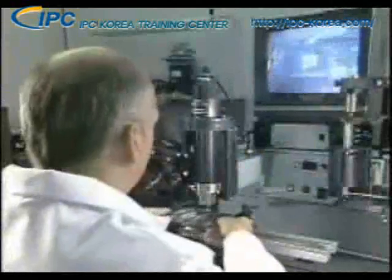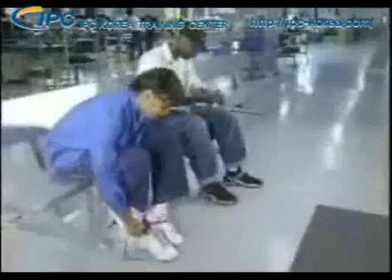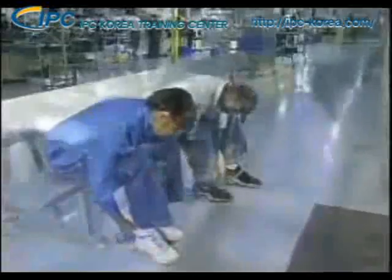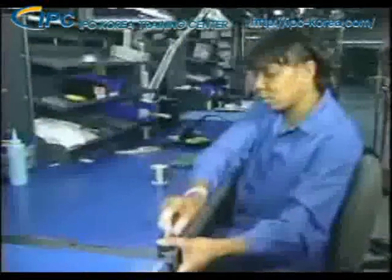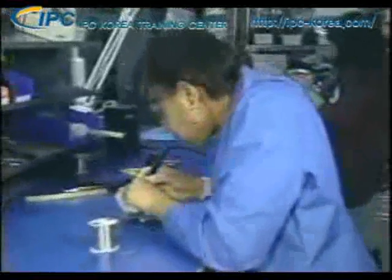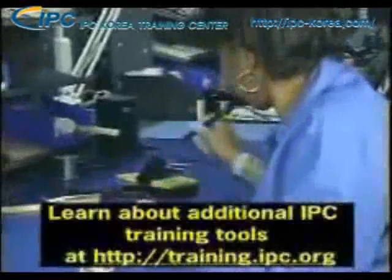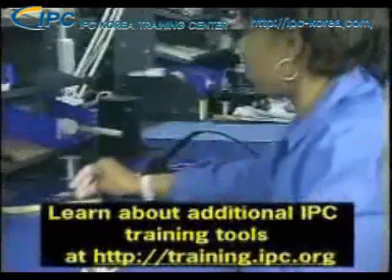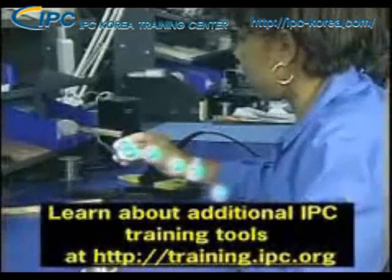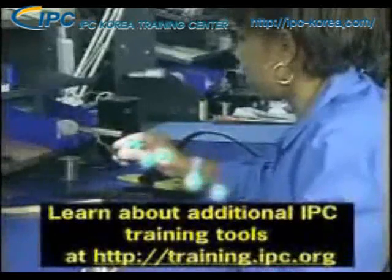So, since we are the main culprits in the destruction of ESD-sensitive devices, let's begin by taking a look at what equipment is available to reduce the risk of ESD damage from people. The idea is to drain off charges in a controlled manner before they reach the devices. To do that, all conductive surfaces and our bodies need to be connected to a common grounding point. If a static charge comes into contact with any partially conductive surface, this contact safely channels the charge away from ESD-sensitive devices and neutralizes them into the earth or ground.